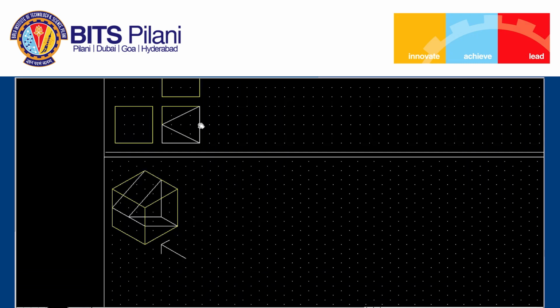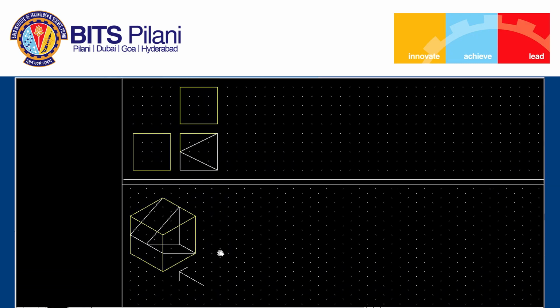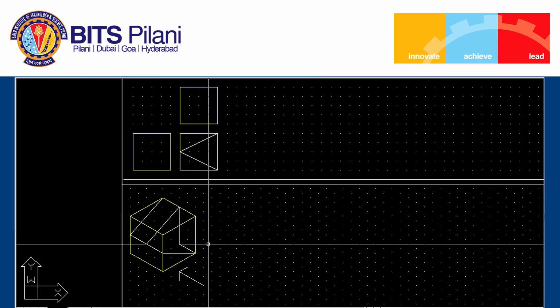Let us now start the top view. In the top view, I can see this inclined surface and this inclined surface, and the apparent area can be seen. I can locate those points. Okay, so the top view will be very easy here. It is from this corner till this corner, which will cover the entire length of the object, and along the depth, 2 grid spaces for this surface. Similar way for this surface.